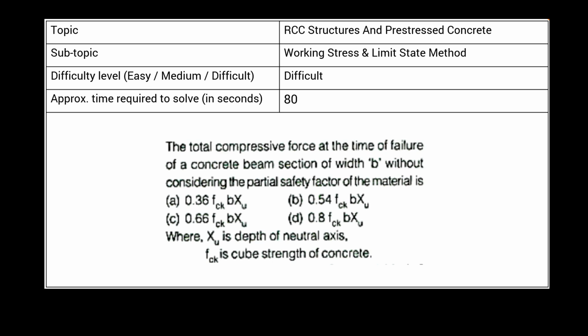The paper setter's expectation is that the student should know well about the bending of beams and the limit state method. What they test is how well the student is able to integrate the concepts of bending and limit state method. The difficulty is more because they need to know a lot of tiny concepts clearly. The students' approach for this and questions of this kind should be to draw the stress block, mark the stress and strain values by choosing the data appropriately, mark the profile of stress and strain across the depth, and find the volume of the block.